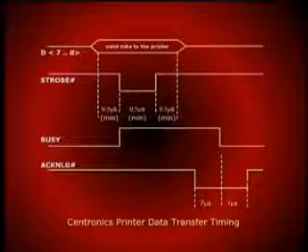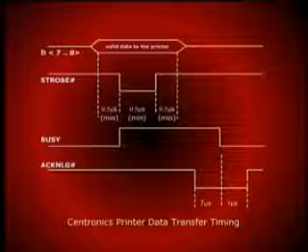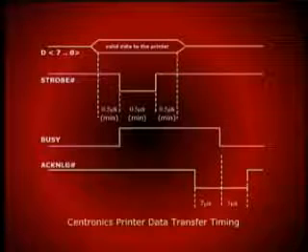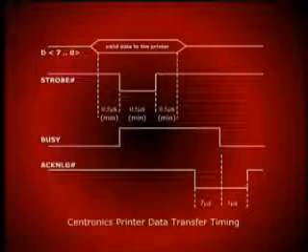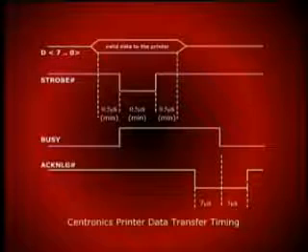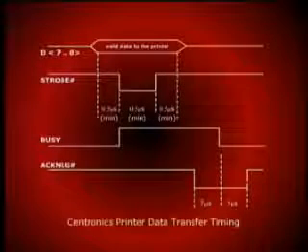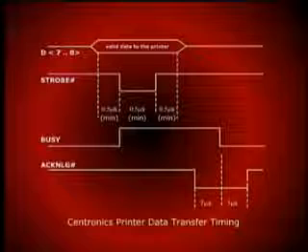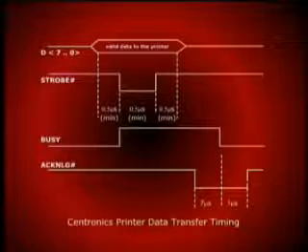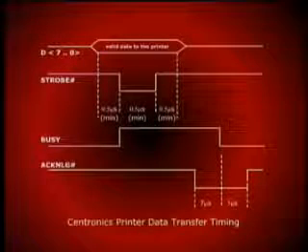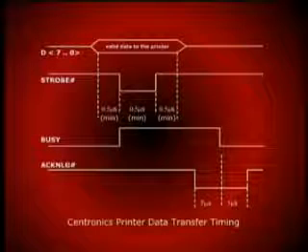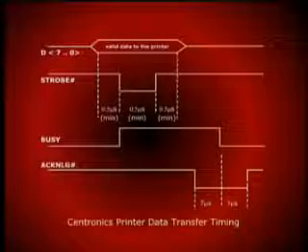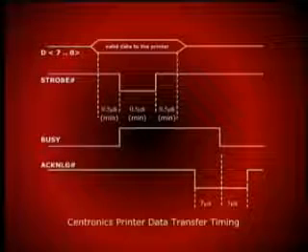As soon as the strobe low signal is applied, that is, strobe goes low, the printer activates its busy line, which is physically pin 11, and therefore it indicates to the CPU that additional bytes cannot be accepted. The CPU can monitor this status signal over an input port, which would be defined as an address read from this particular port. We will call it an input or I/O status port.